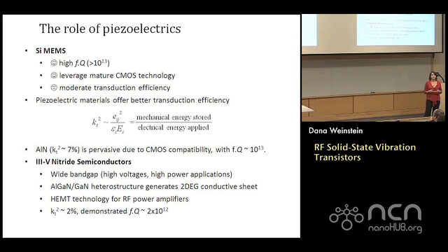If I really need a low-loss system, say in the case of front-end filters for your radio, I need a low-loss system which maybe uses piezoelectric materials. As I mentioned, quartz, right? Well, actually, quartz has roughly the same transduction efficiency as electrostatics. It's pretty bad. It was chosen for its temperature coefficient of frequency. But there's a lot of materials out there which have very high piezoelectric coefficients, right? Very good transduction efficiency from one energy domain to another.